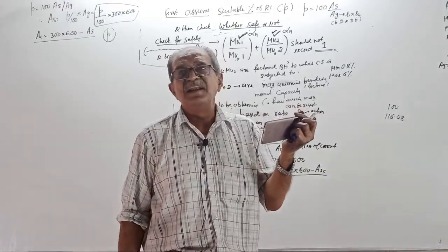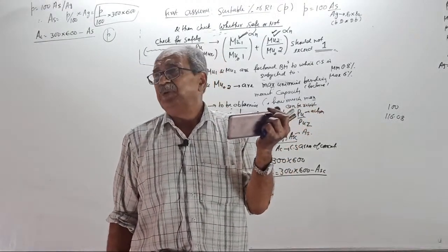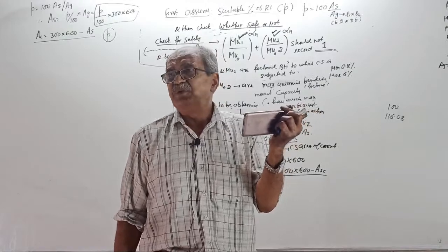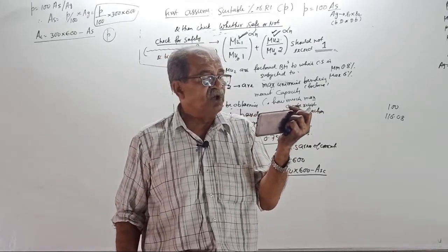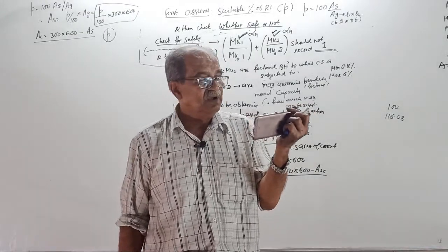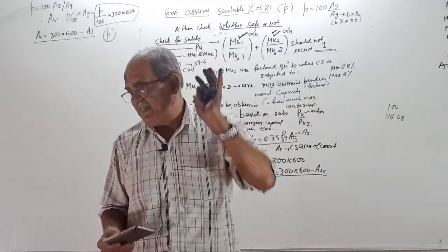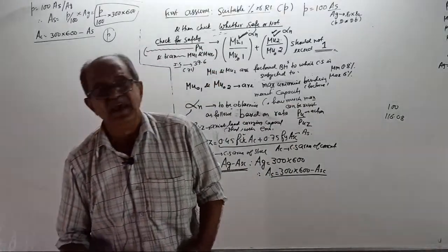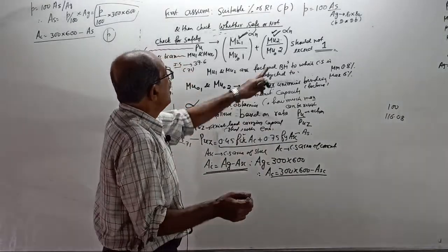They want little reserve strength. They do not want to reach the critical state. So people will tell good design with a good margin of safety, not 1. Tell me one answer. Correct? How much? Around 0.8. If it is around 0.8, that is 20% reserve strength. That way you decide. Anyway, that is your personal choice. IS code told it should not exceed 1.